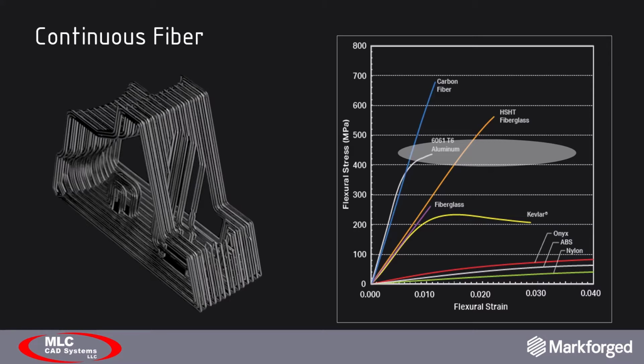Each fiber has a unique value proposition to help solve a number of different problems. For example, when leveraging carbon fiber, you can actually print parts that exceed the strength of 6061 aluminum, which was big for Acme Audio because a lot of their parts are custom bracketry and custom components that are structural in nature to the audio system.